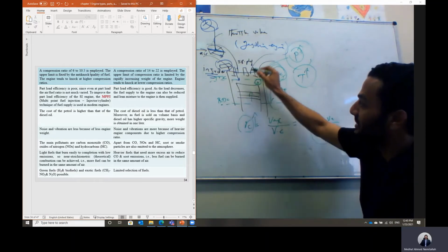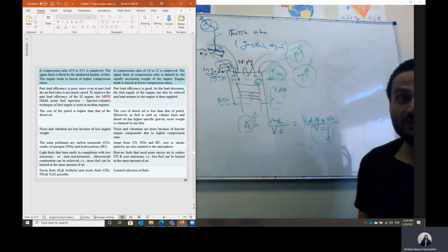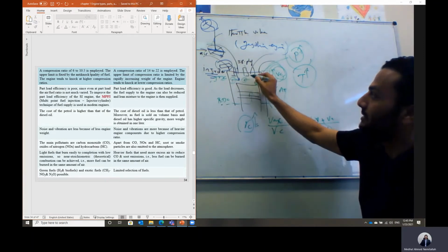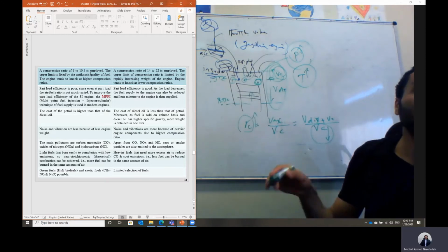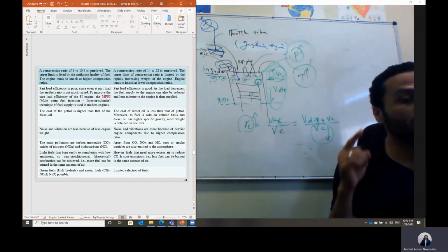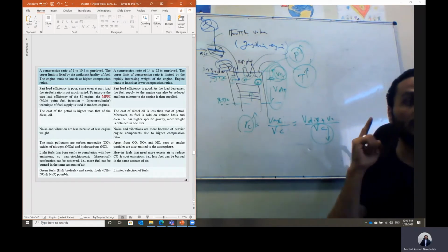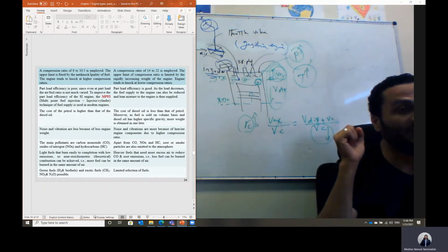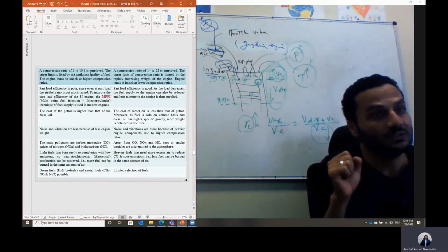And after some time while the piston is moving, we'll have self-ignition at another point, and self-ignition at a third point, and the spark will initiate the combustion as well. So it is a lot of explosions during the compression stroke. This is what we call the engine knock. You will hear the engine knocking, like knocking on a door. It is a kind of noise of the engine, and it is very dangerous.